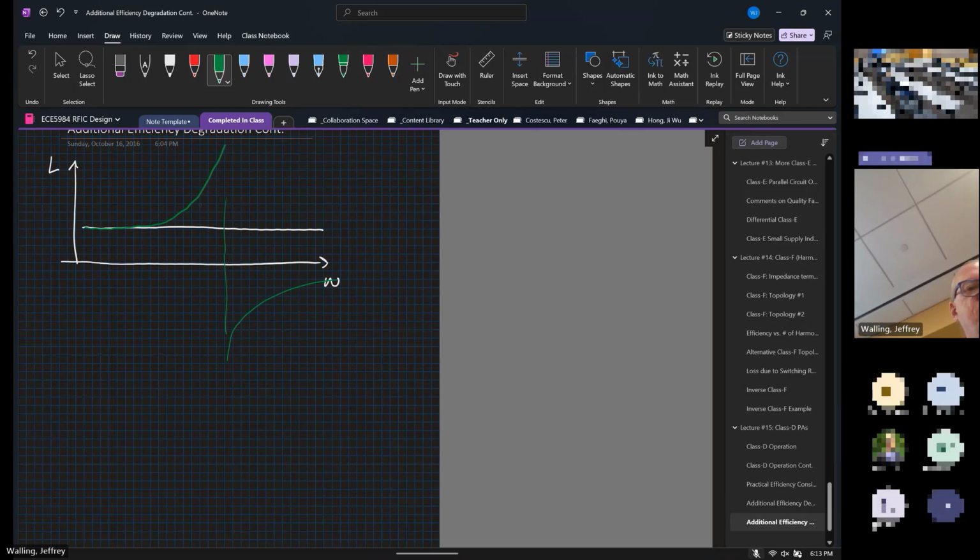So the challenge you have is you need to operate at some frequency. So you're trying to operate at this frequency. The closer you get to this slope, and the higher the quality factor, the faster the rate of change of the inductance is. So if you're trying to make a design and center it, and you're getting close to that slope near the self-resonant frequency and the Q is high, you're subjecting yourself to quite a bit of variation in the component. That's why you're trying to keep the self-resonant frequency well above the point where you're going to use the inductor.